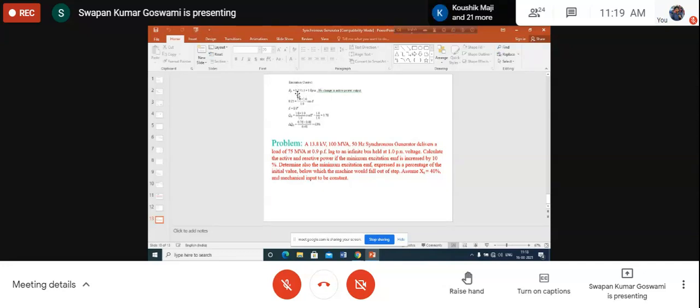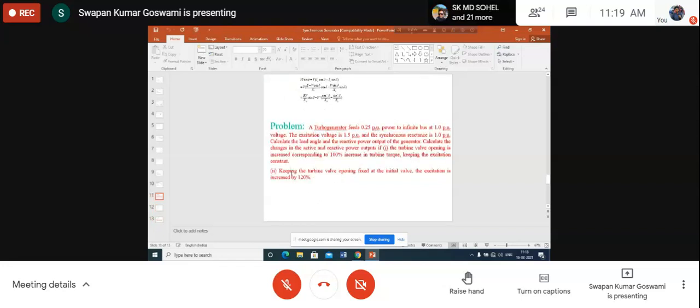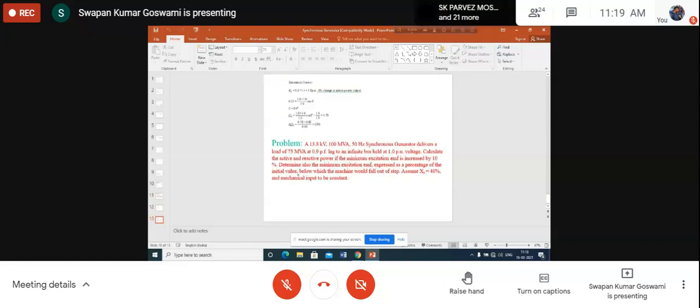There is actually an error in the statement here. It was not "increased by", it will be "increased to" 120%. As the problem is treated, it will be 120% of the initial value, so it becomes 1.8 per unit. You have not increased the active power input.